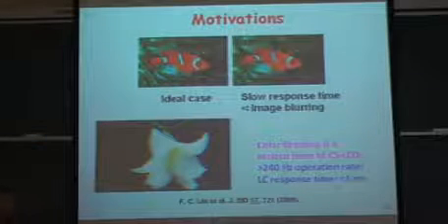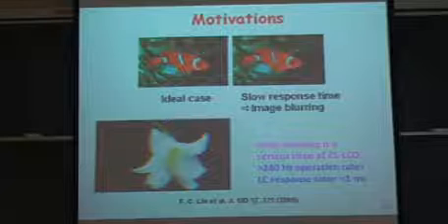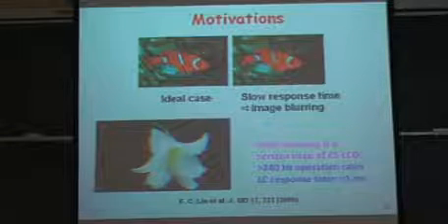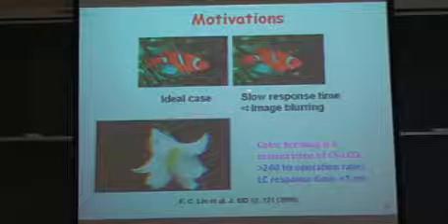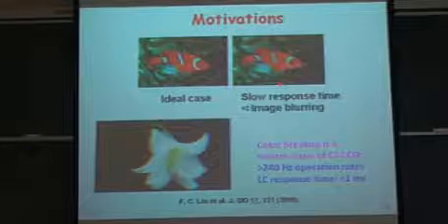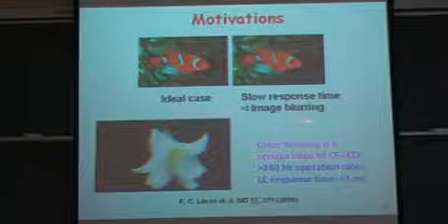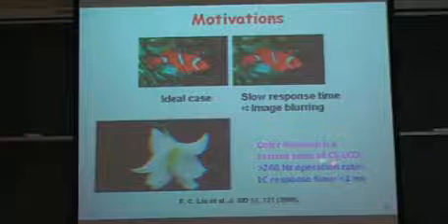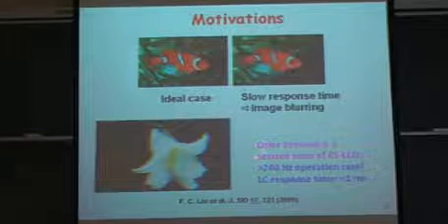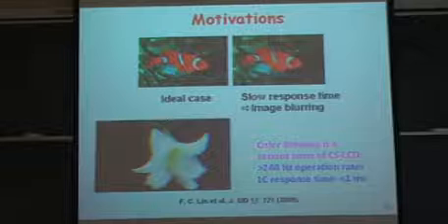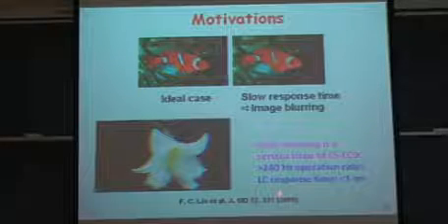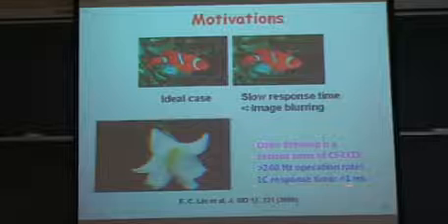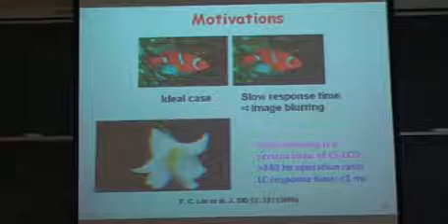Now I'm going to talk about the dopant effect on the negative liquid crystals. Actually, this slide is for liquid crystal display. In liquid crystal display, slow response time can induce image blurring. And also in color sequential display, the slow response time can induce color breakup. So it's very important to develop liquid crystals with response time less than 1 millisecond.